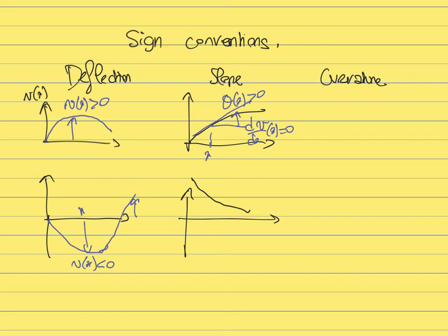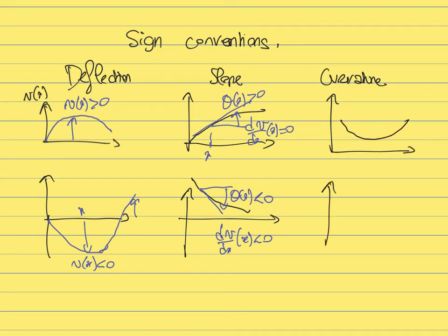On the other hand, if the beam is making an angle like this with respect to the horizontal axis, which is clockwise, then this is what we will use as the negative sign convention. So this is going to correspond to a negative derivative of the deflection of the beam at a given point. Now, when it comes to the curvature, again, we need to consider two potential cases where the beam can either have a convex shape like this or a concave shape like this.